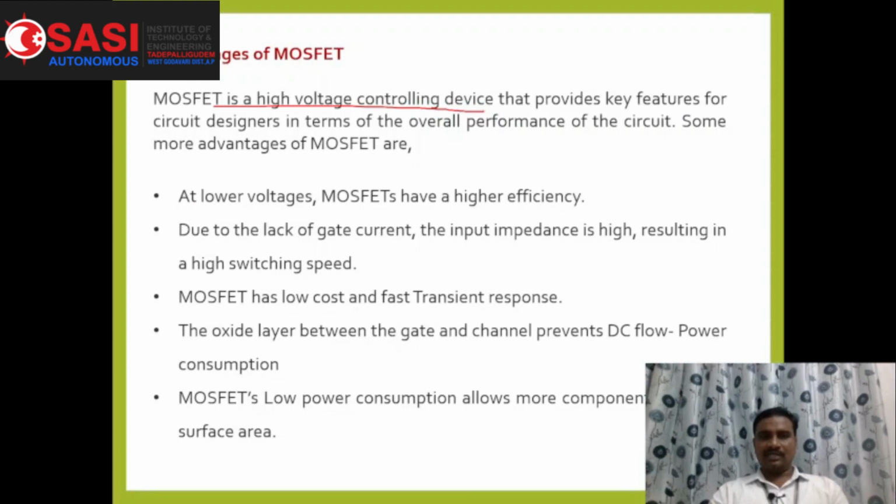At lower voltages, MOSFETs have a higher efficiency, and due to the lack of gate current, the input impedance is very high, resulting in a high switching speed. So this is one more advantage. High switching speed is one more advantage in this MOSFET. And MOSFET has low cost and fast transient response.